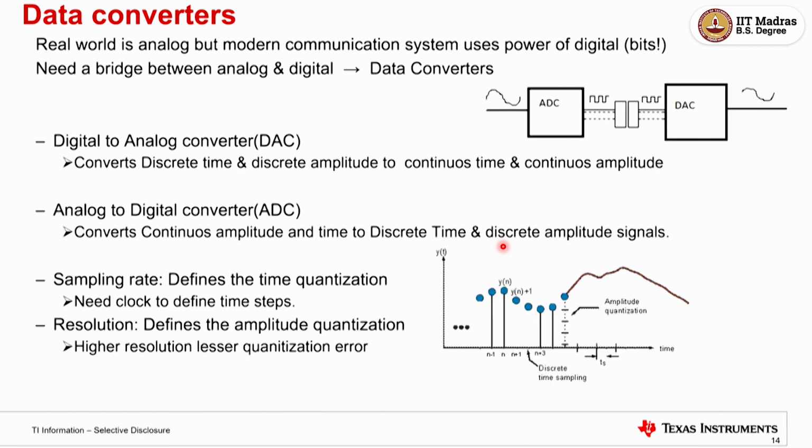Okay. So now once you have an ADC, how do you convert analog to digital? So you need a time base now. Analog signal is just free moving. I'm discretizing in time and amplitude. That's what an ADC does. So you need both. You need discrete time. You're not representing it in infinite time. You're saying time slots. That's what discrete time signal means. So your waveform has to be discrete time represented, and also amplitude is not full. You have discrete levels that you want to define for analog.